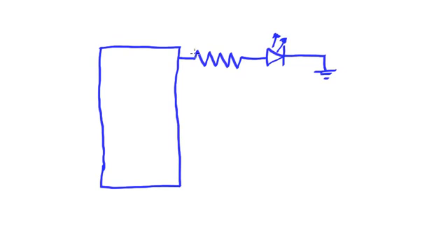In this particular example, then, in order for this LED to light, I would need to provide a connection to the VDD or the V positive end of the power supply. That can be done internally in the microcontroller whenever we go high. So in this example, then, this LED will light whenever we make that connection, and then having a complete circuit to ground, this LED will light. So when it is configured in this fashion, this is referred to as sourcing because the microcontroller is providing the connection to the V positive. That means the other end of our device has to be connected to ground.